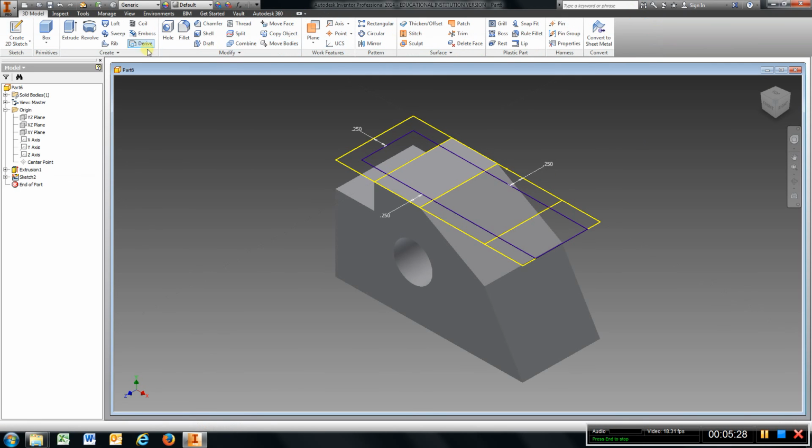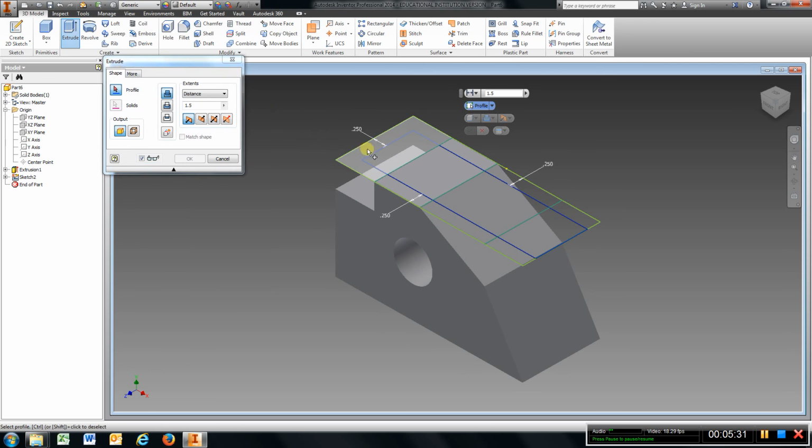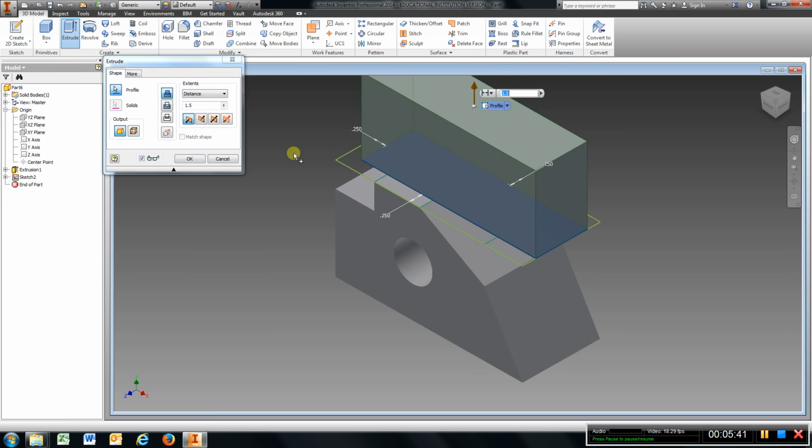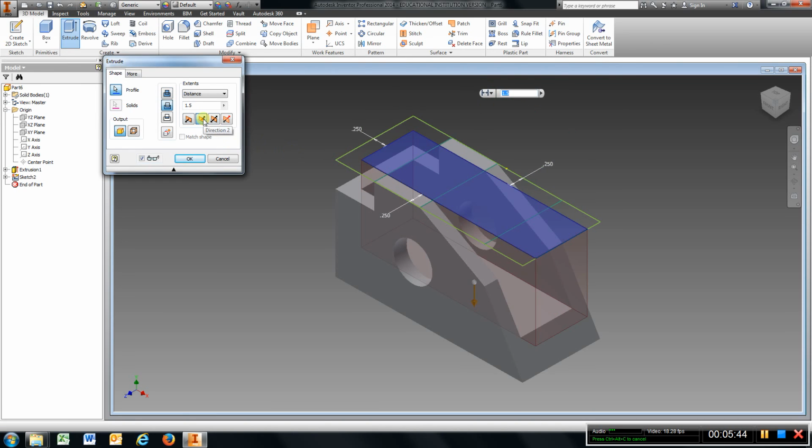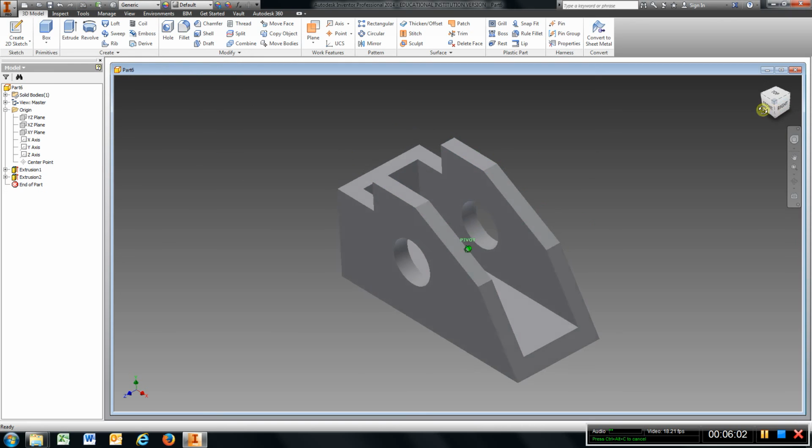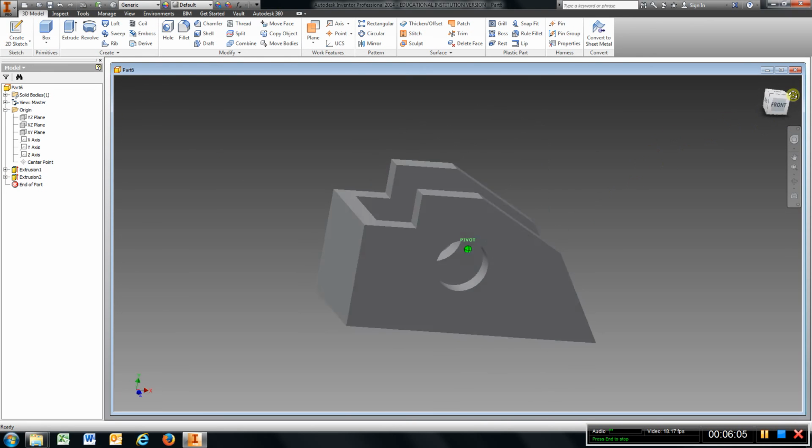Finish the sketch, go to extrude, and you have to hover here till you get only the inside rectangle. You don't want to pick anything out like that. You want it like that. Click it, and remember, we can come here and change directions there. And since this part is 2 inches tall, I want to leave a 1/4 inch thickness at the bottom, like we have all the way around. So I'm going to type in a 7 right there. Hit OK. So with that little shortcut, we can complete that whole part.